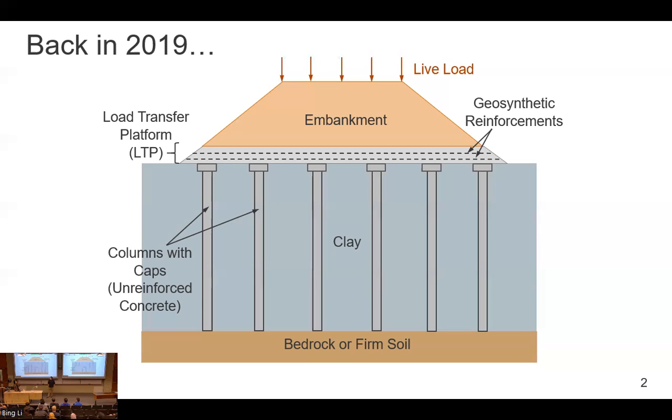In our software suite, RSPile uses that. If you were to do your p-y analysis, which is LPile, RSPile also does that. But if you were looking at some exceptional circumstances, like your pile groups may be very closely spaced together, where you're not sure what the p-y curves are, then in that case, using numerical analysis like finite element would be very useful.